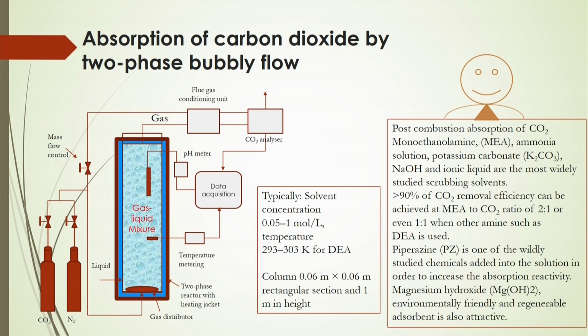that hold up of the gas will give you more surface area, because we have already studied in our previous lecture that the specific interfacial area depends on the gas hold up, and it is estimated by 6 times epsilon g divided by the diameter of the bubble. So, if we produce finer bubbles, more interfacial area is produced, and more mass transfer can be observed. One of the important variables here is gas flow rate. If you increase the gas flow rate, you can get more hold up.